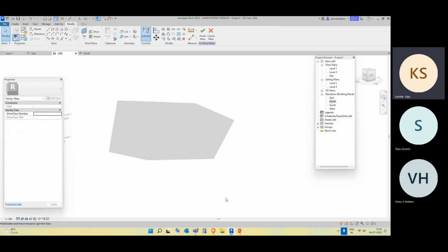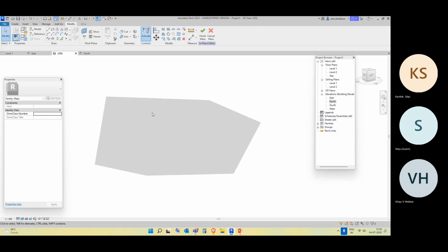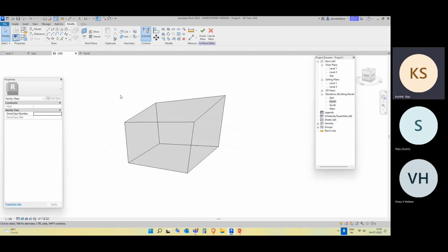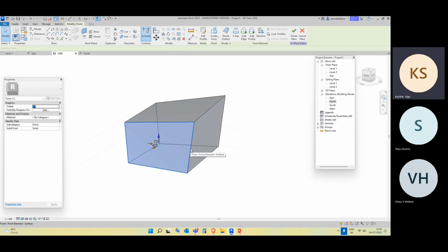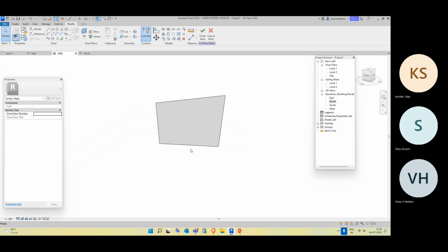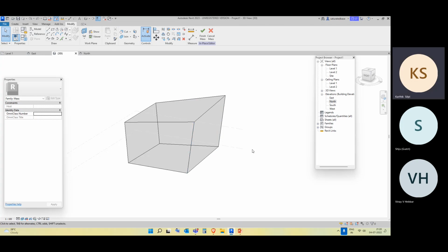And I want to create a glass wall in all the directions except the base. Right? This is my requirement for this geometry. I can just select any tab or delete that particular tab, or sorry, not deleting. We cannot, because this is a shape. If you want to create a glass structure on 3 sides, or on 4 sides, and one side you want to have a floor or a roof, you have to first finish the mass once.